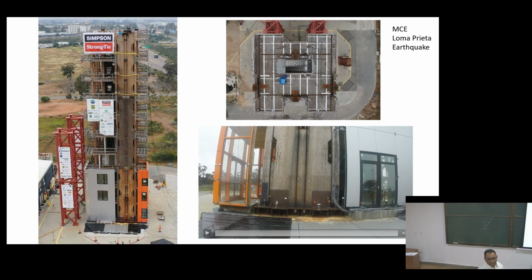Northridge ground motion, which is a unique type of earthquake, large displacement is coming. And that's what we wanted also. Our favorite go-to is the Northridge earthquake. That's what we do a lot. Then we also did Mexico City, Tohoku, but we tested like 45 to 48 different ground motions at different levels. So it was just a suite of ground motions.